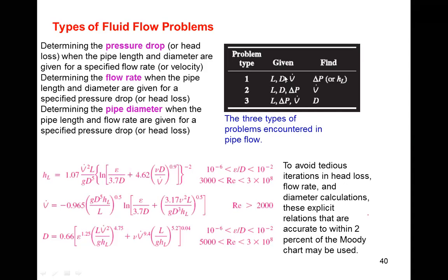So first we are talking about the design, just to calculate the pressure drop. Pumps we will talk about later on. So this is one problem. Another problem is that a person has given you this much as my permissible pressure drop. This much pressure drop I can permit. I know the length and the diameter. Please tell me what should be the flow rate. This is another type, the class 2 type of problem.